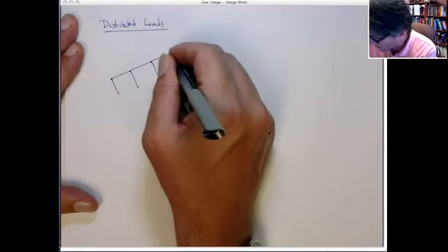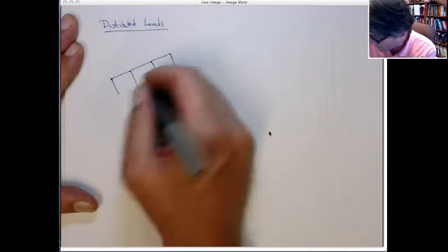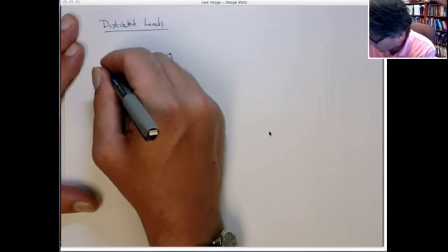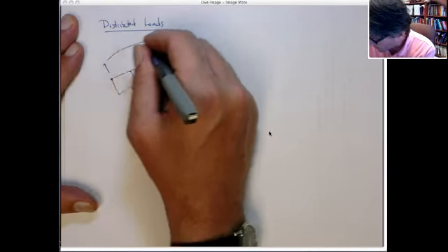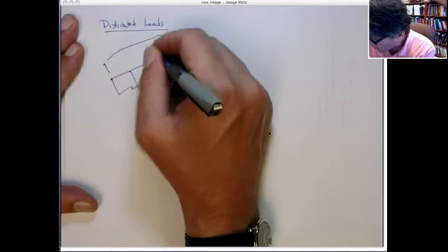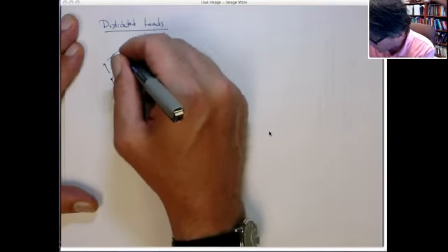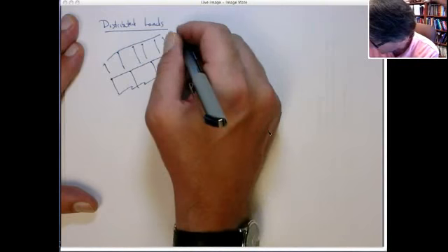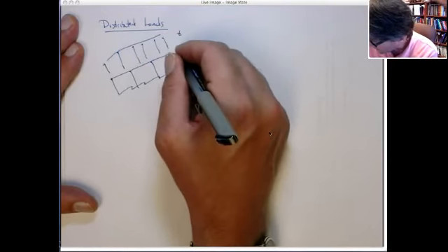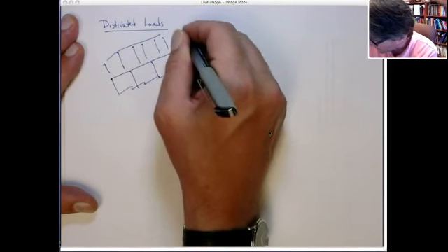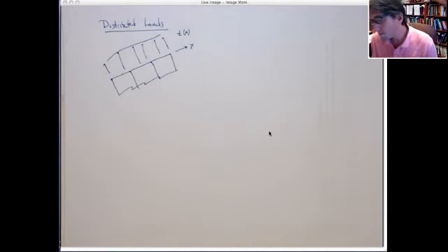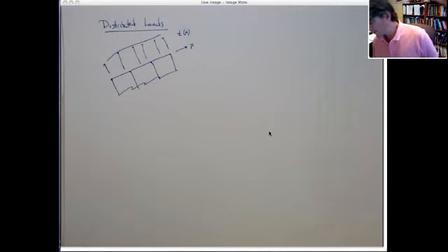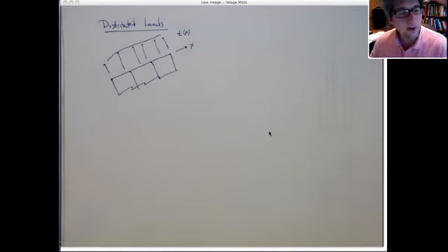Let's say we have a mesh. Well, here I'm drawing a Q4 mesh, right? And we have some defined traction that's distributed along the edge, and it has some distribution. Let's call it T, and then let's give a dimension in this direction, X. For now, I'm just going to consider distributions on straight edges. My derivations can be a little off for curved edges, but I think it's close enough. And most of the stuff we deal with is straight edges. The math gets a little bit much for the curved edges.